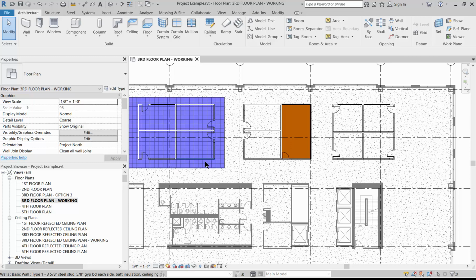Now how we show flooring is not very defined. It really is going to vary depending where you're going to be working, so each office has its own standard. But the crucial point with any drawing should be it should be legible. So the scale of your drawing might dictate how you decide to show a different finish, whether you're using a pattern or these days color printing is getting much more affordable and accessible, and a lot of times we're just showing things digitally anyway, so using color on architectural drawings of all the different types is becoming more common.